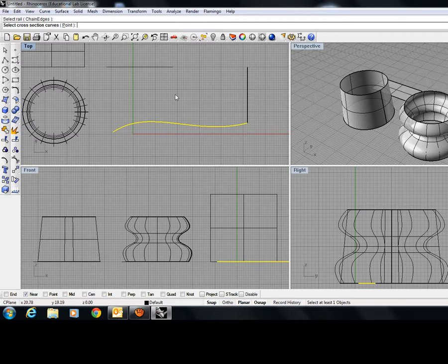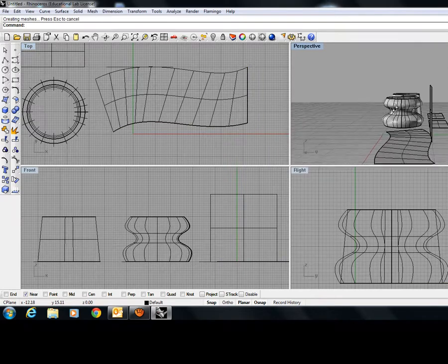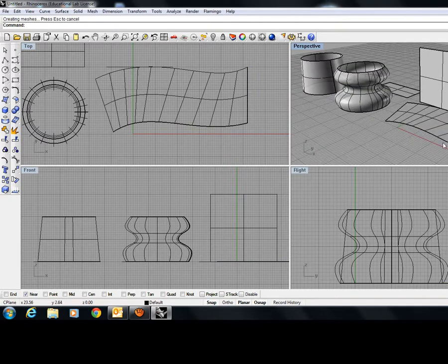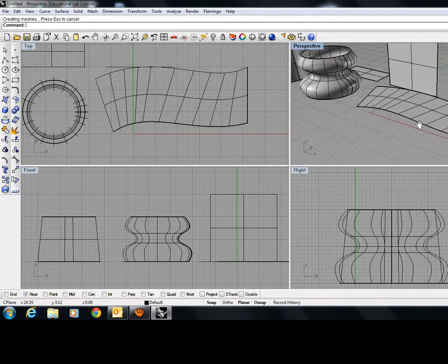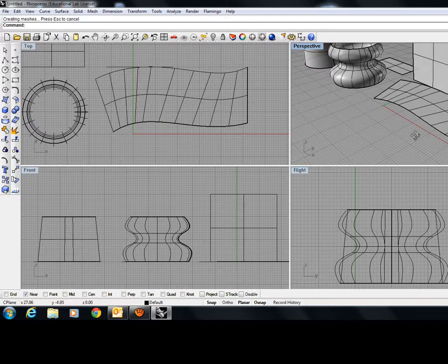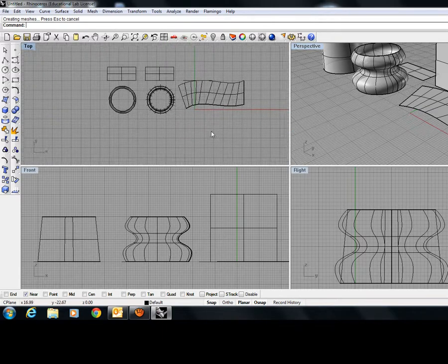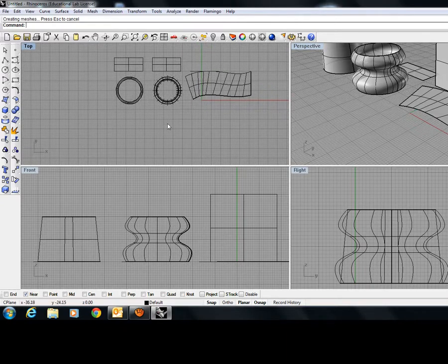I just want it to be steady or the same on the whole line. I have this one. In this case, I have a surface that uses only one rail on all its way. Okay? So that is one sweep rail, as different from two sweep rails, where you need two different rails. Okay, so that is another way of creating surfaces.